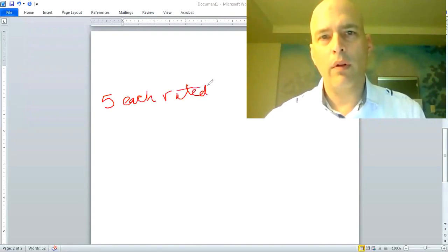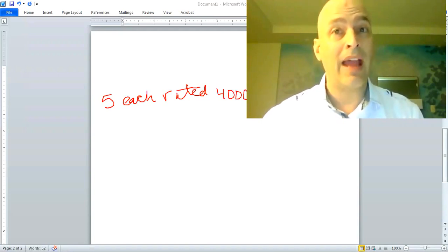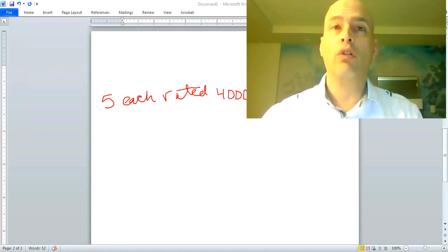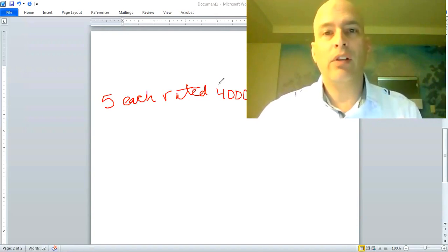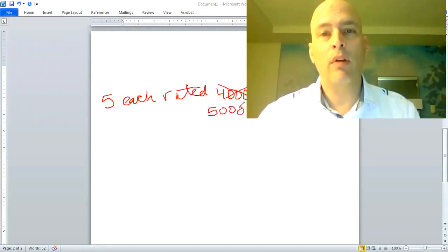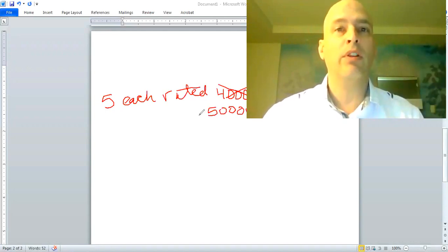for 4,000 watts. Remember, the article tells us that we can't use a value less than 5,000 watts or the nameplate of the actual dryer itself, whichever's larger. In this case, the 4,000 is not big enough, won't cut it. So I'm going to have to get rid of this number, if that was the nameplate of that dryer, and bump that up to 5,000 watts minimum from that table, excuse me, the article. And I would just write myself a note, guys. If I were you, I would just put minimum 5,000 watts right on the top of the table that's on page 71.